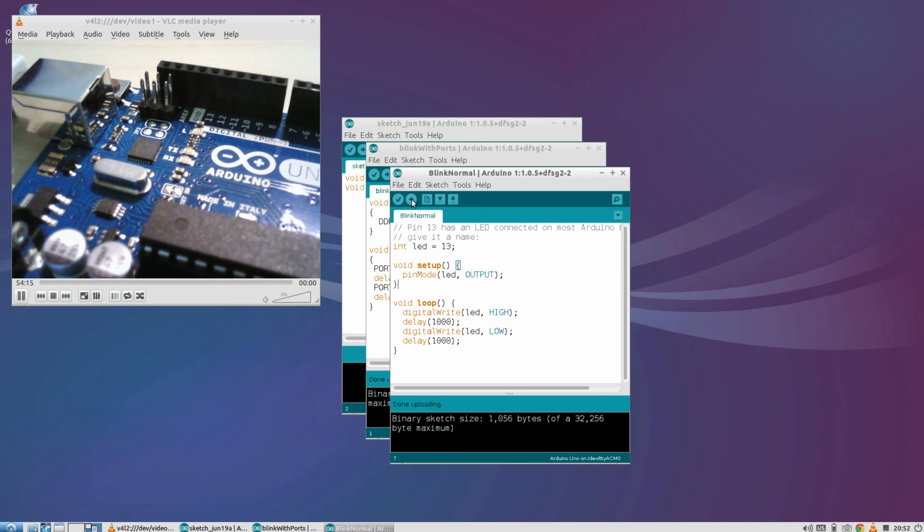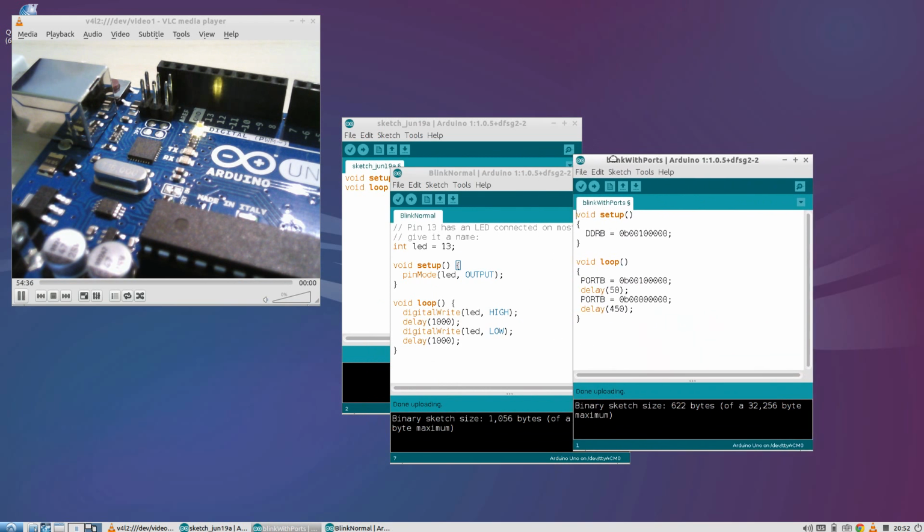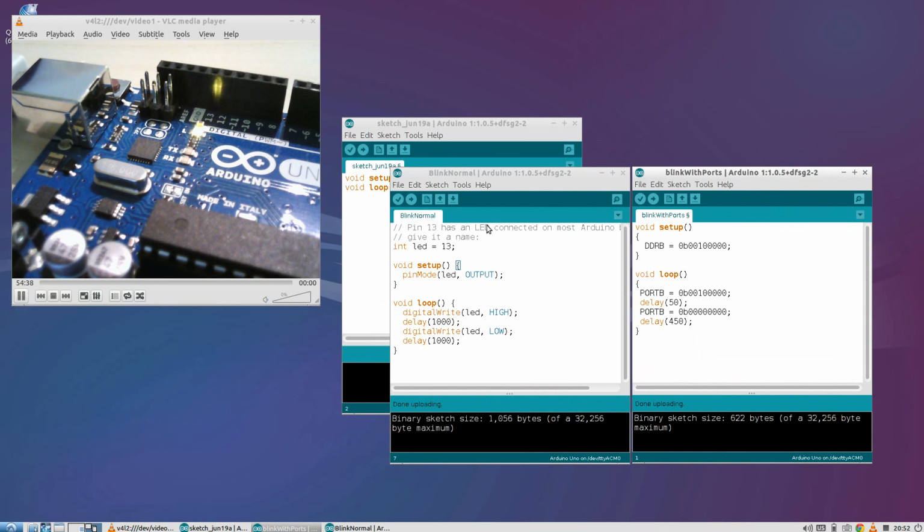That's nice, but what we'd like to do is break apart and expose what's actually going on over here. Pin mode is actually doing some interaction with the LED that's connected to whatever port is inside. So I'm going to move this over to the background and pop open what's actually going on inside, and we can read this side to side. Pin mode is interacting with that pin register I was talking about earlier. Then we can go over here to digital write, and now we're going to say pin 13, we're going to turn it on, wait some time, and then turn it off, and wait some time.